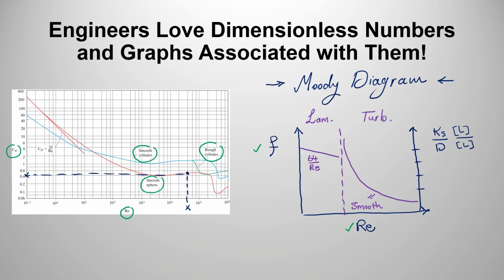So this is the final form of the Moody diagram that you see in your textbook, right? Perfect. So the Moody diagram also was developed by dimensional analysis, having 3 pi's. One pi was Reynolds number, pi 2 was friction factor, and then pi 3 was relative roughness. Now, this is how engineers develop these diagrams that are so useful when you are designing something.